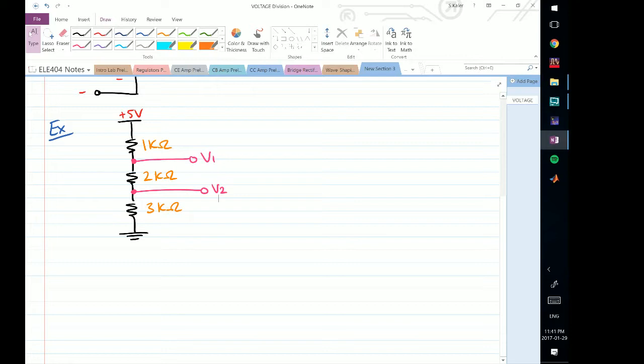Now, one thing we should note is whenever a voltage appears like so, we are assuming this is the voltage between this point and ground. So the assumption is that I will always have, if we can rewrite this then, a ground point here, and that I will call the voltage between this point and this one V1. Now the thing is, we won't want to draw this every time because it will become very messy very quickly, so I assume whenever I have a branch off like this at any node, and I write a voltage here, that this is the voltage between this point and ground.